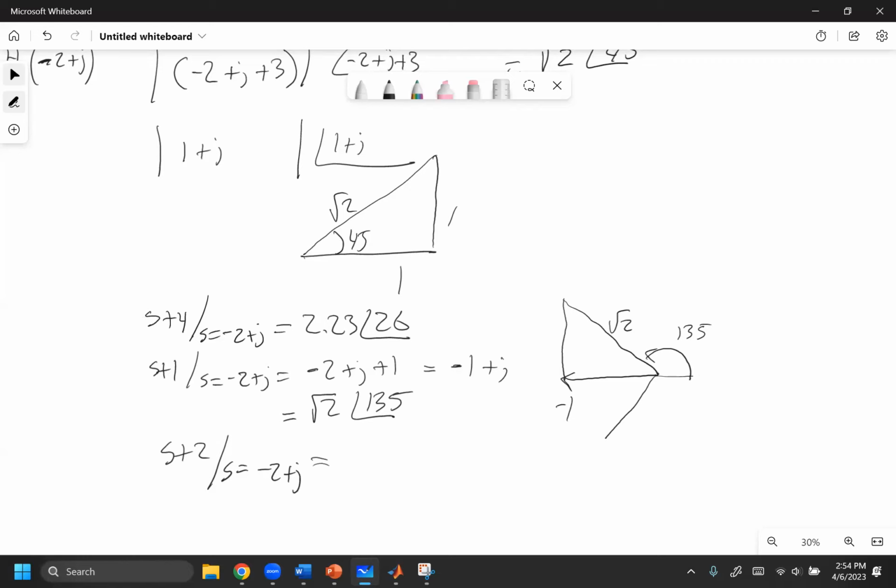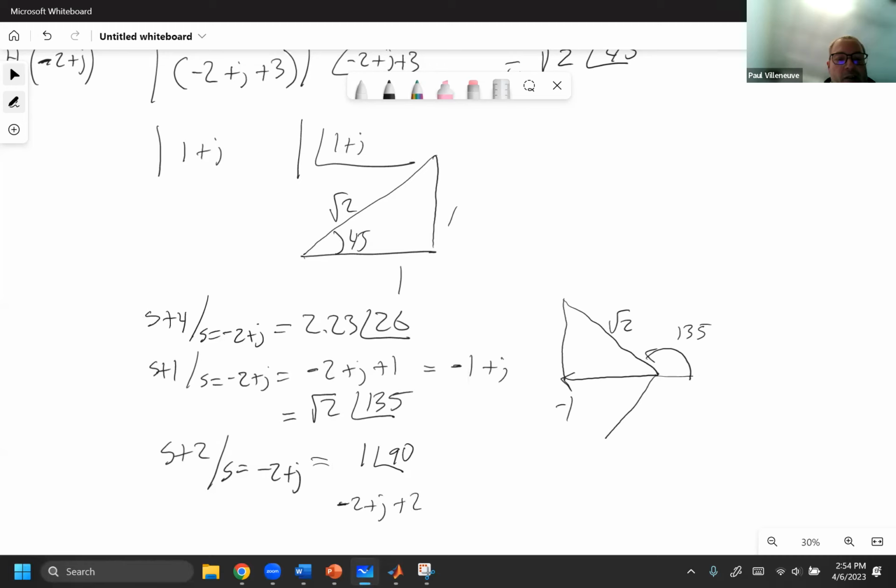If you want, I believe I have the answer for this. All right, go ahead, Tom, help him out. Okay, so you want the magnitude and angle. I got the magnitude of 1 and the angle's 90. Very good. And how he knew that, and you can correct me if I'm wrong, Tom, is because it is -2 plus J plus 2, which is just equal to J. And we know that J is 1 at an angle of 90 degrees.